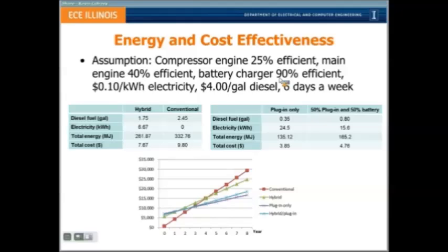I just want to ask, the battery you used is lithium, right? Lithium-ion battery. But maybe most of the batteries in the trucks are lead acid. Right, that's the old technology. So why don't you use that? Good question. Lithium-ion battery has a much higher energy density, and also it's environmentally friendly. If you look at some of the recent electric vehicles like Nissan Leaf and Tesla, those all use lithium-ion batteries instead of lead acid.